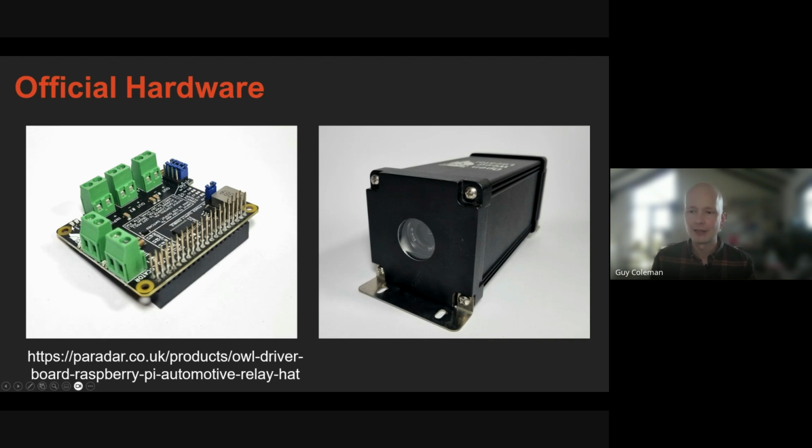And we just added, I think the other day, another pin here, based on some feedback from a farmer in South Australia. He was suggesting that if you could control or enable or disable each of these outputs based on, say, a section control relay on your sprayer, then you could almost integrate it with your GPS. And so that way you can do more selective spraying, I guess. It also means you can control the outputs of the OWL more easily as well. So you can turn them on and off, say if you're going around a headland or parts you've already sprayed.